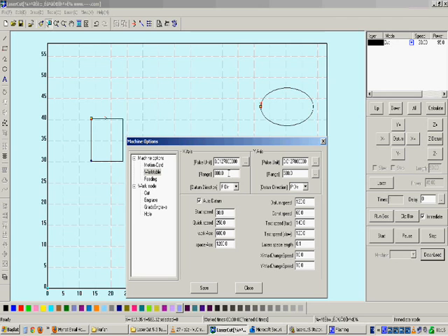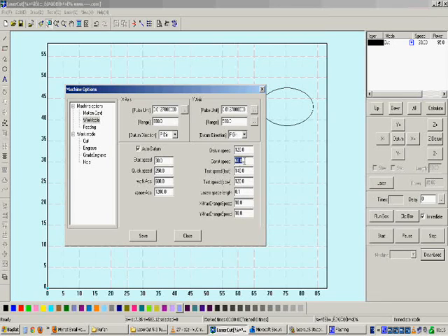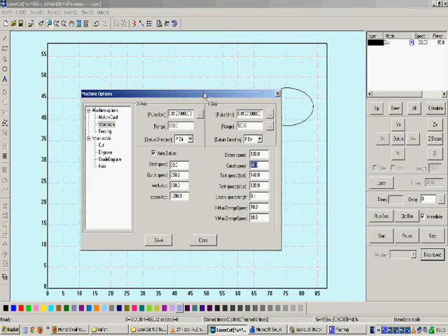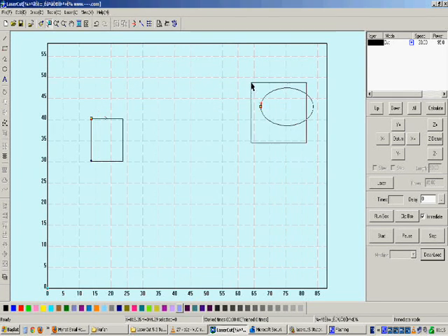But the most important thing that you will be able to play around with here is the start speed and constant speed. The start speed, constant speed, and the cut speed you use in the speed parameters of this part are very crucial and affect the total time of the cutting operation.